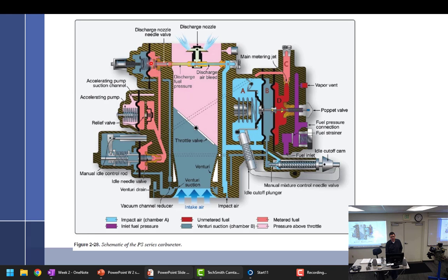Fuel pressure decreases, the idle needle does what? Closes. Why do I want it to close? Clean shut off. What did I write? When pressure decreases, valve closes quickly to provide, not prevent, fast and efficient cutoff. Also maintains a constant pressure downstream.